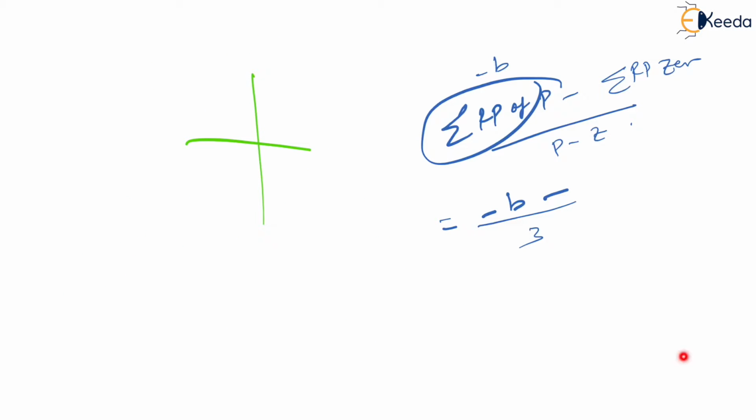So, if you put s equal to minus a, you get this. So, you get minus b. This minus into minus will become plus. So, minus b plus a upon 3. Is that correct? Yes. This is nothing but your centroid. So, if you check out, this centroid will be somewhere close to the origin itself. It means what? This centroid is, let us say here, somewhere close to the origin.